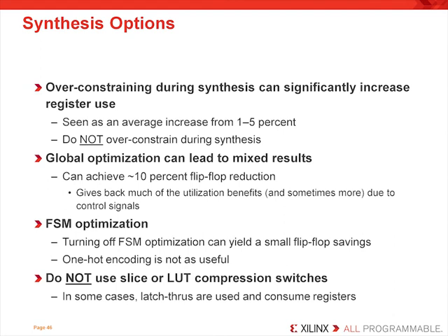Finally, don't use your slice or LUT compression switches. While this does not consume too many extra flip-flops, in some cases latch-throughs were used and consume extra registers. Recall that the slice does not allow you to separate the flip-flop from the LUT, so in the case of a latch-through, the LUT is used and the flip-flop ends up being wasted.